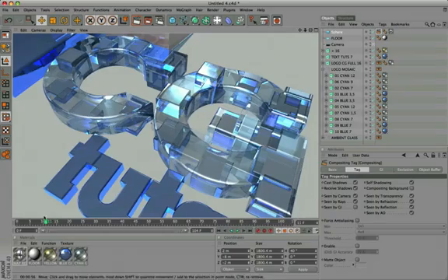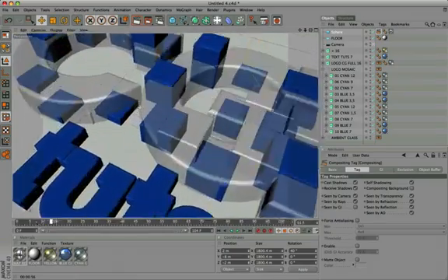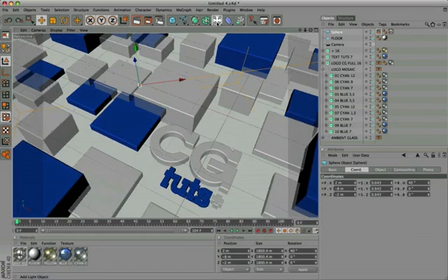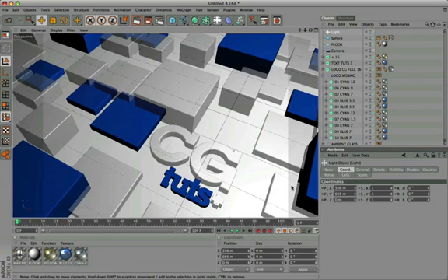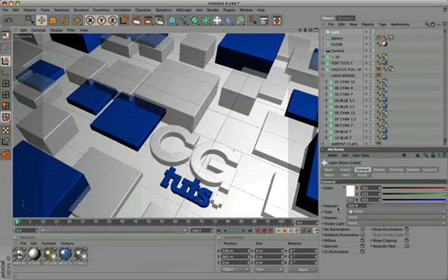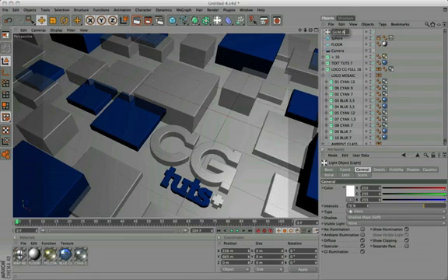The result of the glass material is very brilliant, and should be adjusted with the addition of lights. Enter the first light with the following coordinates: x 556, y 665. In the general panel, change the intensity value from 100 to 70, and activate shadow maps. Rename this light to Light A.